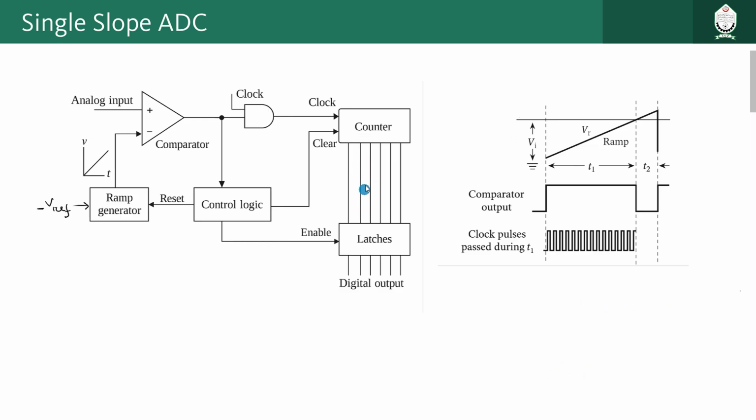And also you will see that the counter is connected with some kind of latches. Latch basically means that whatever signal is coming here can be stored if needed by giving a high pulse through the enable pin. Whatever signal you are providing here is temporary, it can change, but if you give the enable signal, these particular values coming from the input will be stored here for indefinite time until you reset them.